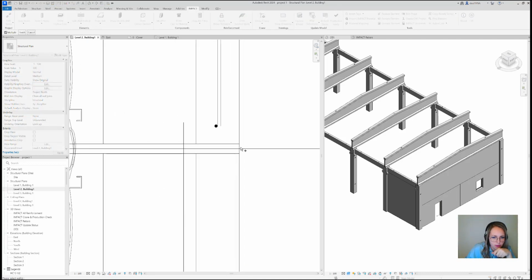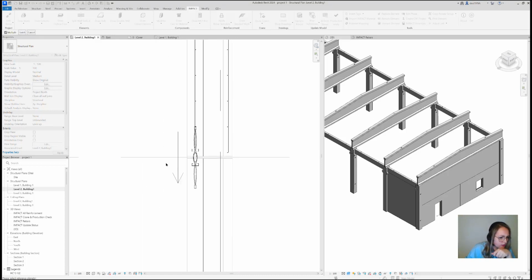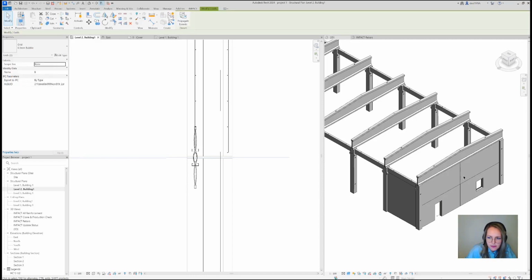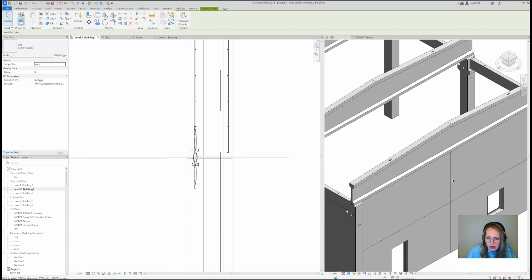Select the wall, it must be the one in here. Okay, and the reference plane is this one. Intentionally, I'm not adding any gap. I just want to split it. You can also do this, okay? I have two walls in here.